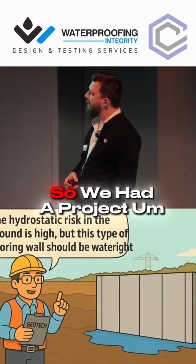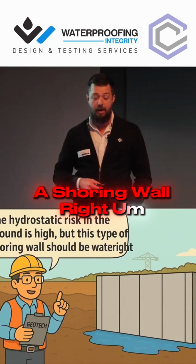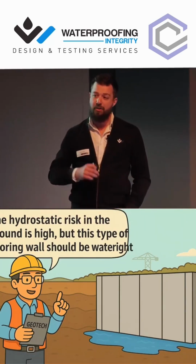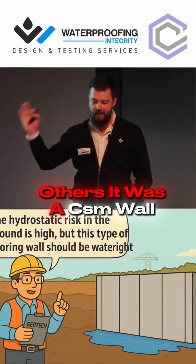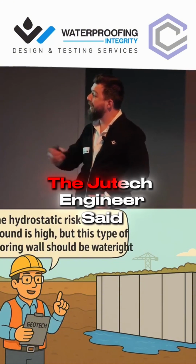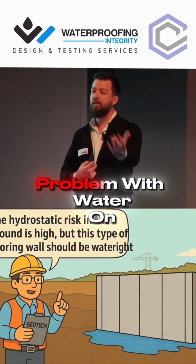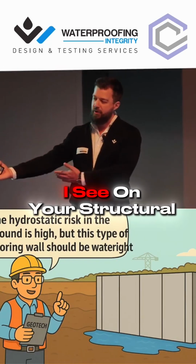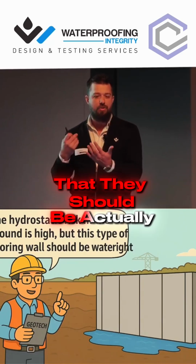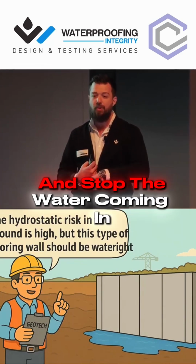So we had a project with a shoring wall, right? And this varied between projects. Some it was a secant pile wall, others it was a diaphragm wall, others it was a CSM wall. Anyway, it was a shoring wall. And the geotech engineer said, hey guys, here's our report, we've done all our analysis. You've got a problem with water on the outside. But I see on your structural diagrams that you've got this type of wall, like secant, for example, that should be able to withstand hydrostatic pressure and stop the water coming in.